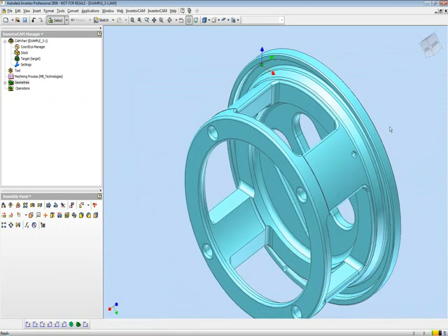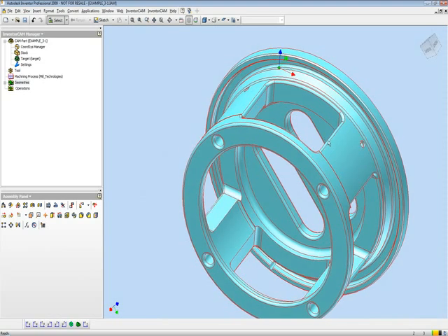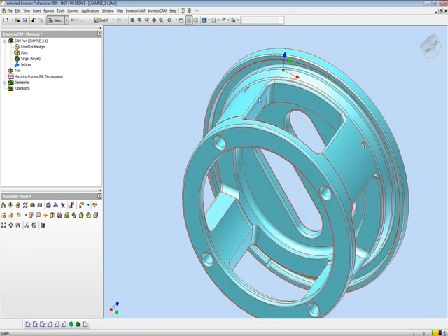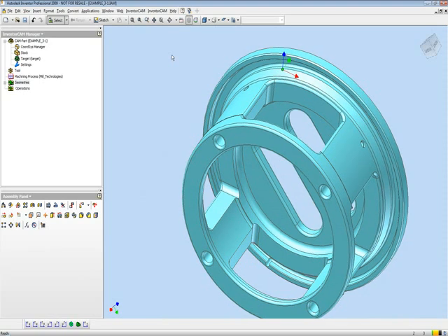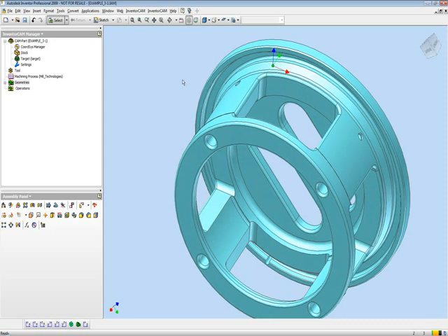Now, in this part we have on our screen, what I'd like to actually do is to machine these fillets around the part itself. Now, this particular part was already machined using a 5-axis machine, but we still have to complete these fillets. Now, the best and the proper way to do this would be using HSS morphed between 2 curves. In other words, I'll be working on the surface between this shape over here and the bottom shape of this curve itself.